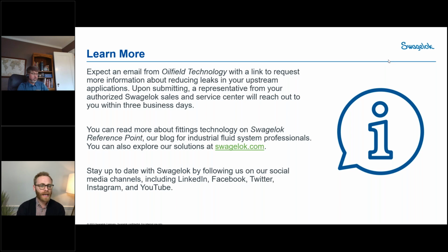A question that's come in is asking what type of online sealing material you would suggest for a valve gland packing leakage, where the hydrogen leak is at 650 degrees Fahrenheit and 350 PSIG. Oh wow, that's specific. So for hydrogen, first of all, it's a very difficult media because of the small molecular size, and so for a seat on a valve, we usually recommend metal in that case.